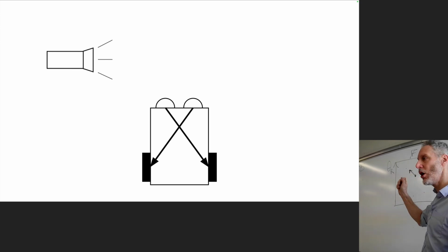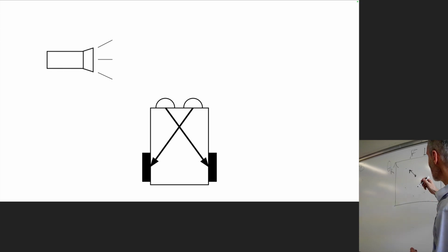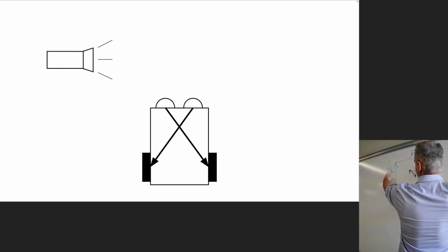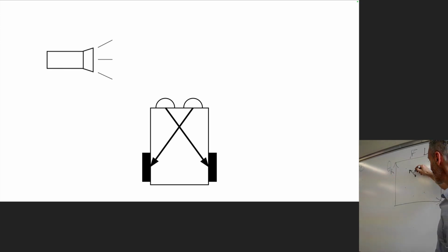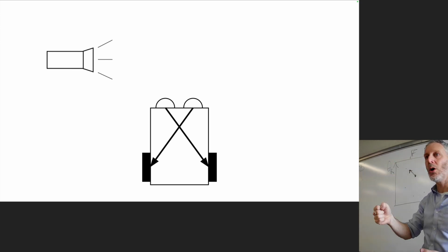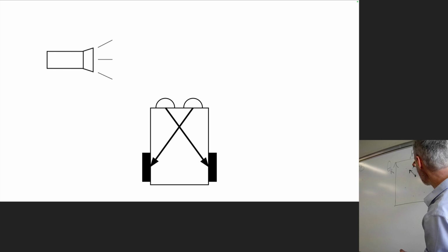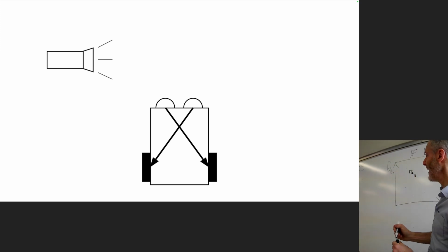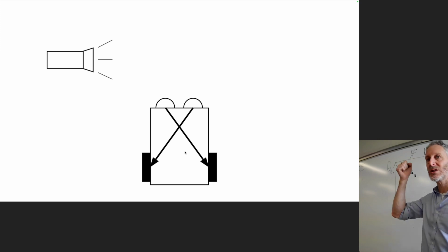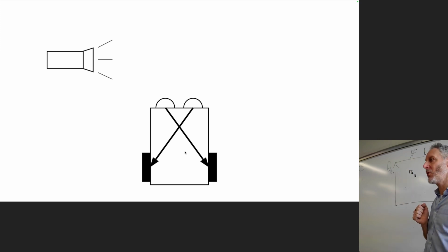We are going to know, thanks to the gradient, that if we make theta R a little bit larger, and if we make theta L a little bit smaller, we know, it's guaranteed, that if we take a new pair of values along this direction and drop it into the vehicle, it's going to do a better job at whatever we want it to do. That's the intuition behind gradient descent.